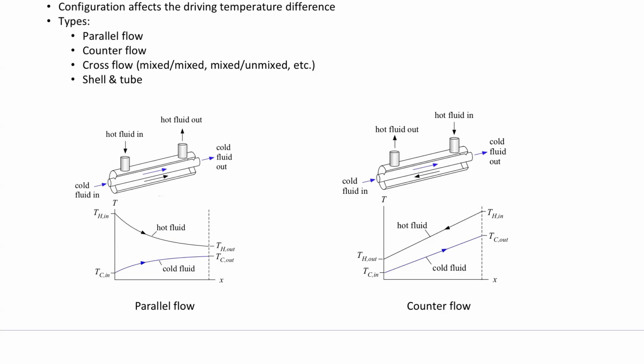So it's much more common to do the counterflow, unless there's some reason where maybe you don't care about how effective your heat exchanger is, or say one of the fluids has a really high capacitance rate compared to the other, then maybe parallel flow is okay. Or say there's some geometry where you have two sources here and your outlet's way over on the other side of the building.